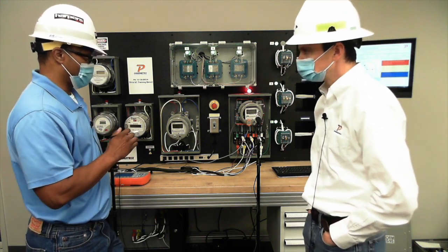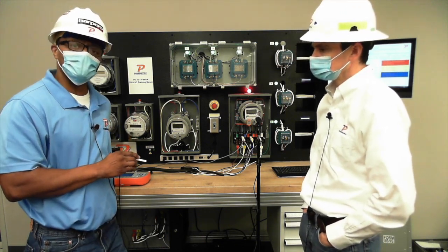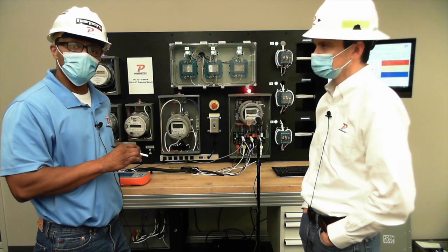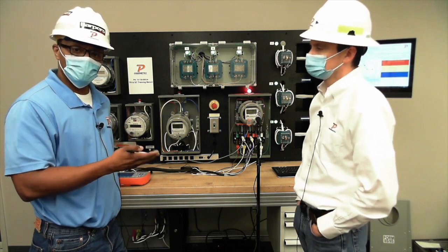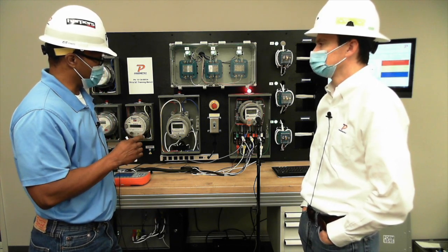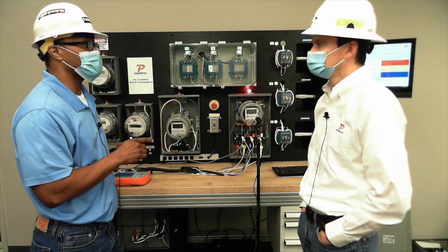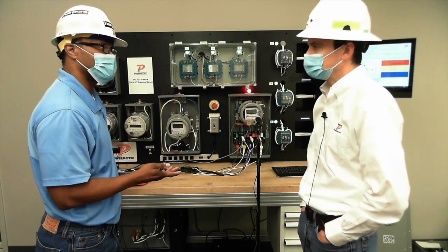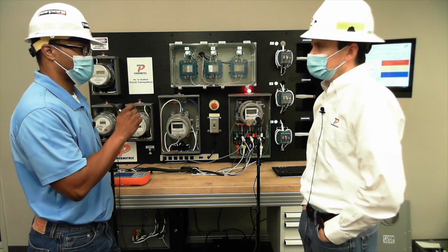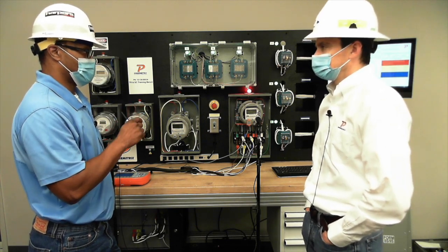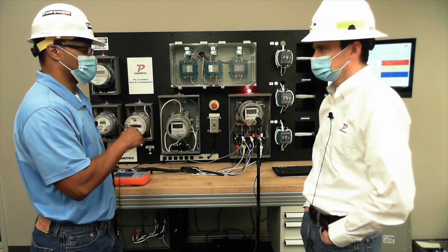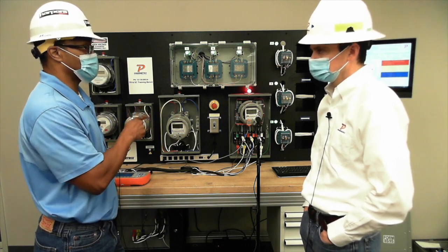Then what I would do is I would go into my PowerMaster 7 series, and I would use manual load box control, and I'd run 120 volts at 2.5 amps. And then I would hit previous and go out there and run it as a customer load test. Yeah. And then I would test that meter. So once I'm done with that, I would then go back, hit previous, save the data, hit previous, and turn off my manual load box control before I start disconnecting stuff.